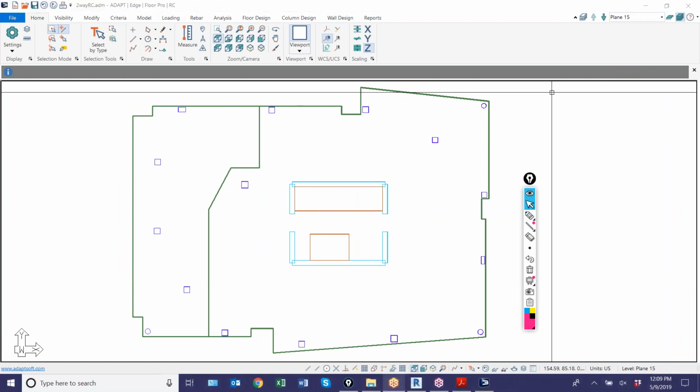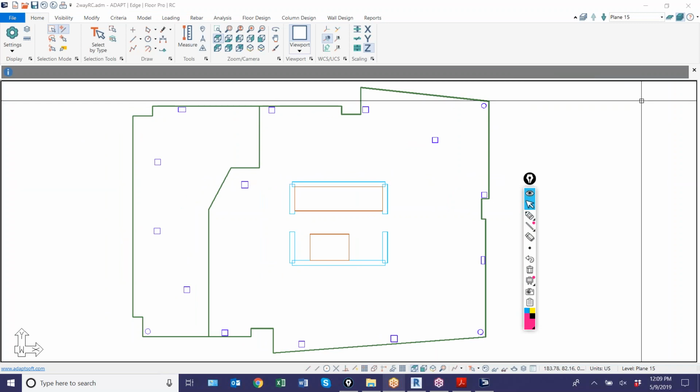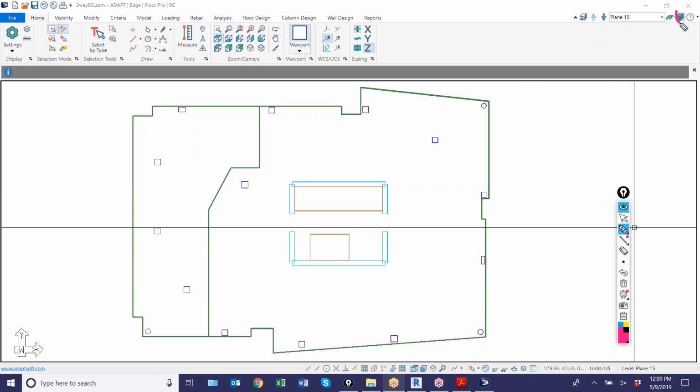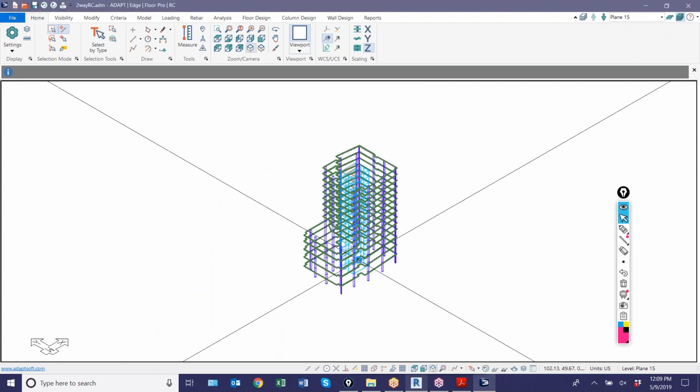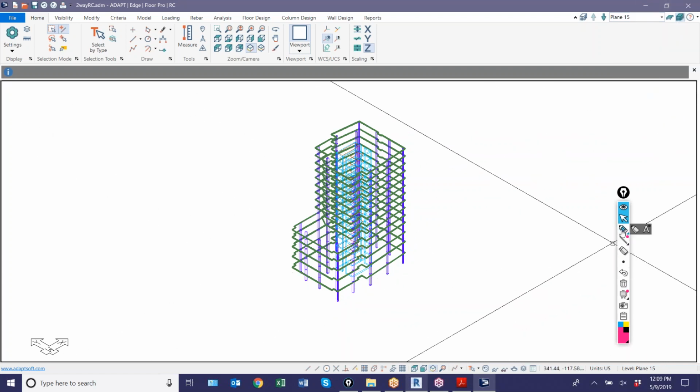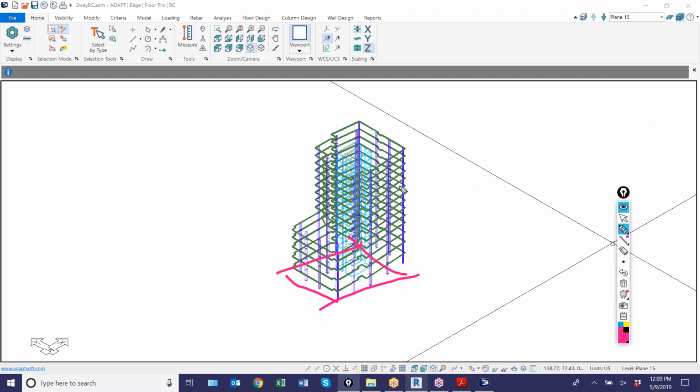Once we enter the modeling space here, you can see that we automatically go into a plan view in what we call multi-story mode. So multi-story mode is this nice button here. The one next to it is single level mode. Single level versus multi-level. And these are important to note because not only does it graphically represent what mode you're in, but analytically, if I analyze this structure in multi-level mode, the program assumes supports at the base of every vertical stack. So at the very base level of all the column and wall stacks, we use a fixed condition. And that can be changed in the criteria settings for multi-level fixity and single level fixity. I'll show you that here in a moment.